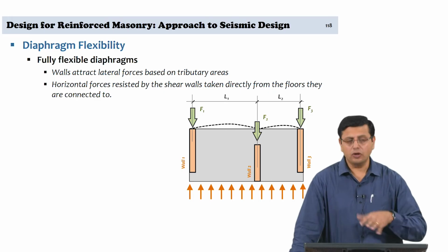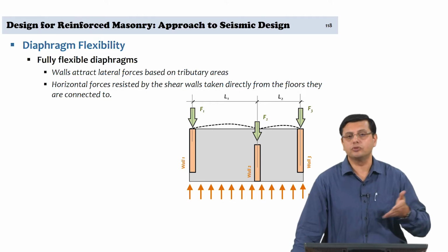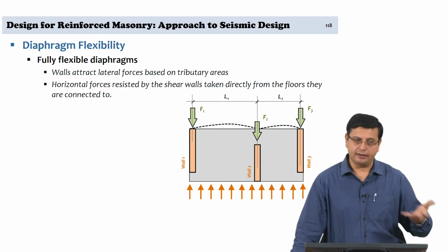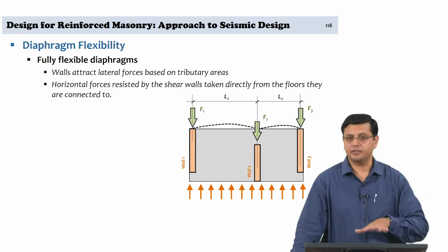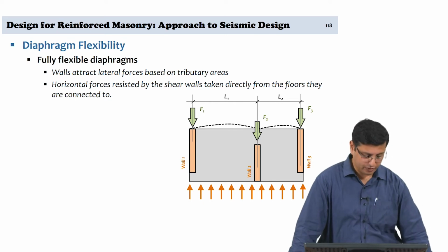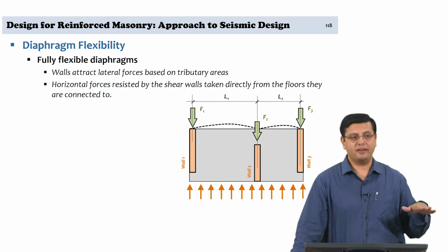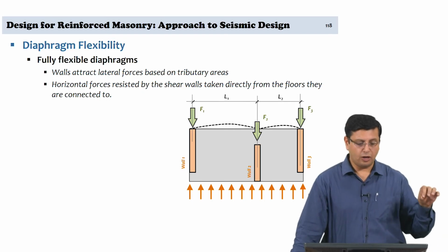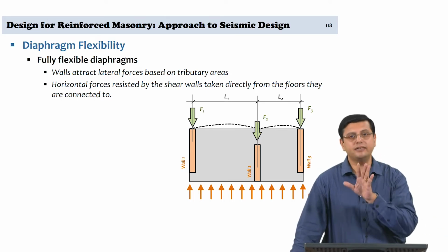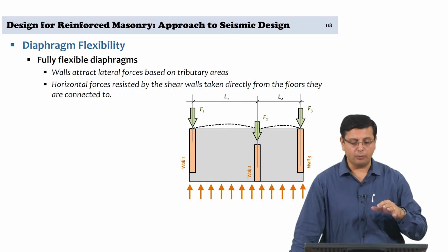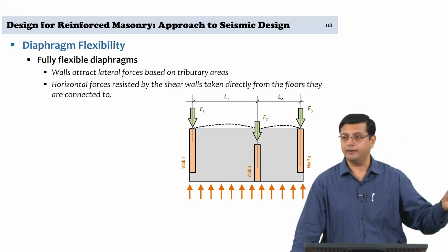So, of course, in modern constructions we are not often choosing to design with diaphragm flexibility. We are typically going with reinforced concrete floors, and hence this sort of a situation may not necessarily be encountered. Okay. So, with that we now have the total framework, from definition of the seismic input to arriving at what the wall, the pier, should be designed for in terms of a combination of shear force, bending moment and axial force, and that is where we began our component design.